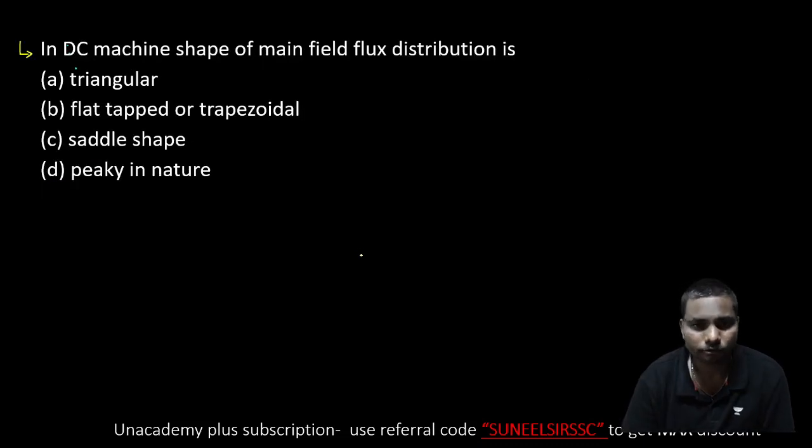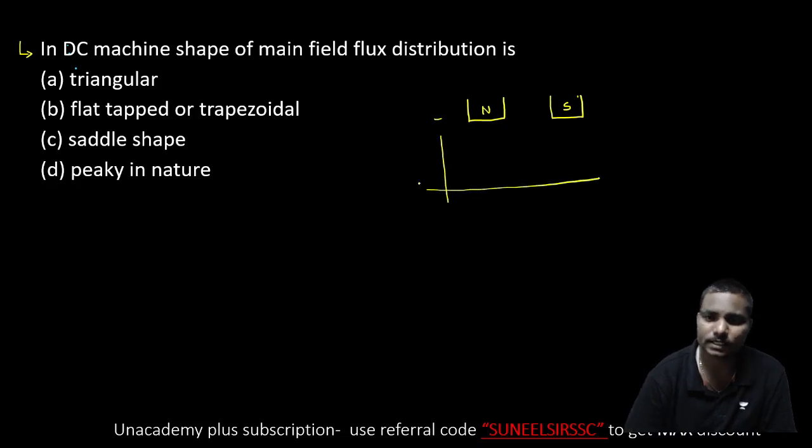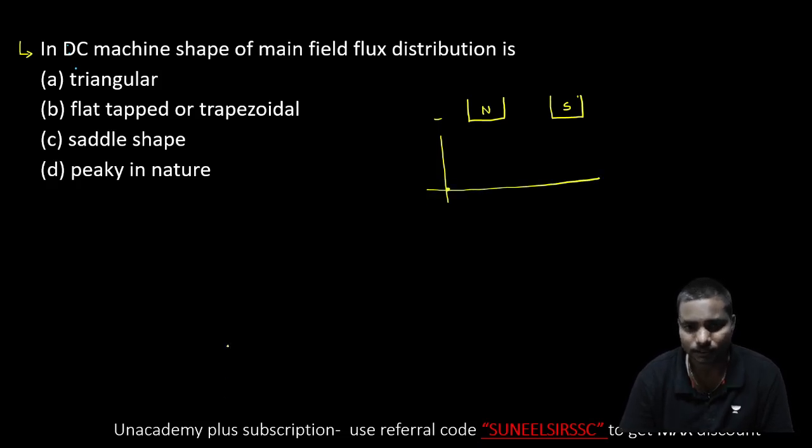So the shape of the main field flux distribution. For example, I have taken the poles in horizontal manner, north pole, south pole. Here we have some air gap. If we have air gap, it means reluctance is more. If the reluctance is more, the flux distribution will be less. Flux is inversely proportional to the reluctance.